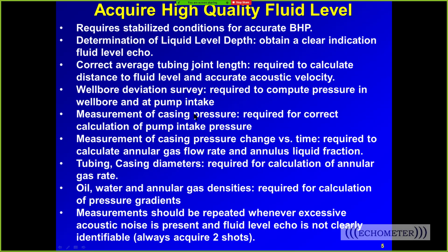So we need a 0 offset. We need a pressure transducer that is calibrated and accurate, and that your 0 offset hasn't changed from day to day or from the last shot. If your 0 offset changes a lot, that can mean a problem with your cable.